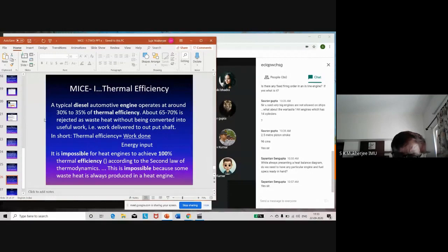The eductor, or a venturimeter, same thing, is a device where high-pressure water produces the vacuum. Under very low pressure, the boiling temperature of the seawater drops to 40 degrees centigrade. The moment the seawater starts boiling at 40 degrees centigrade, the vapor that is released is condensed, and that condensed water comes out as distillate, which means fresh water. So from seawater, we can manufacture fresh water without any extra cost, and that device is called a freshwater generator.